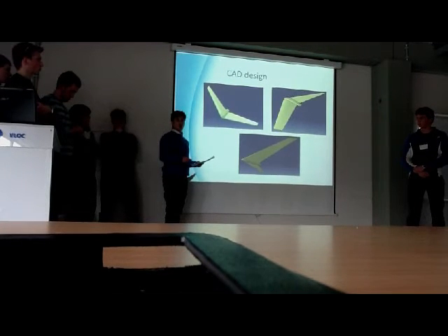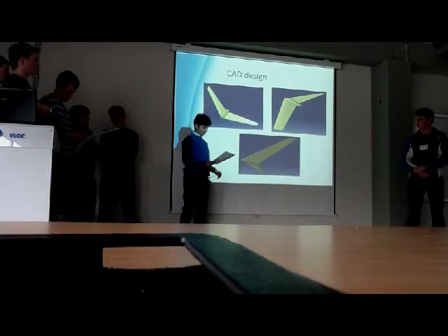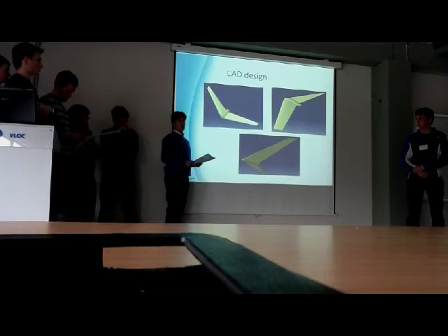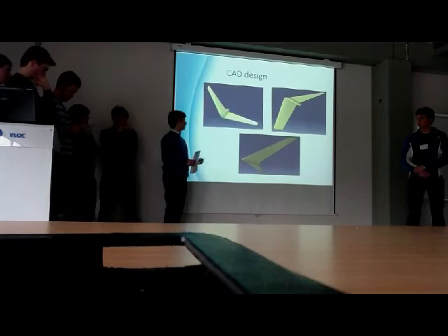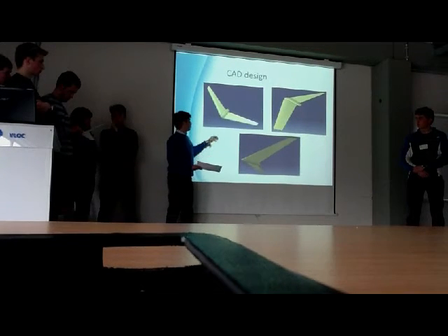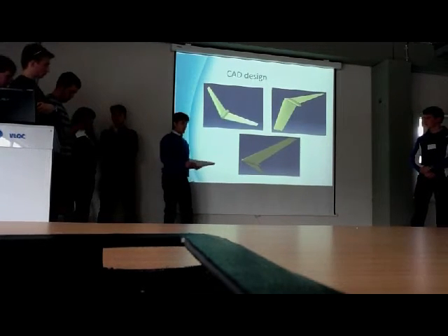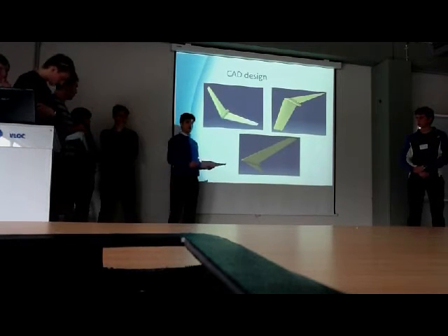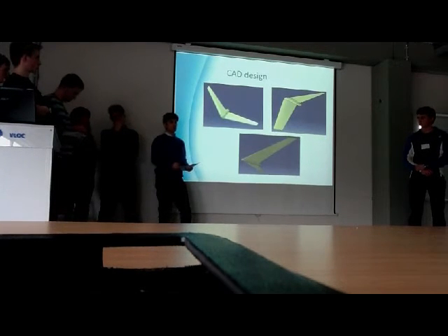for stress, and we found that the worst condition is not proportional to the surface, but to the deflection in this length. And we found a value of sigma of 14 newtons, so our initial prediction to use a thickness of the airfoil of only 1.5 millimeter is respected. Also with torsional and flexional resistance. So we've done, as Peter said at the beginning, an initial idea of the weight and the structure, and then tried to optimize it. That's all.